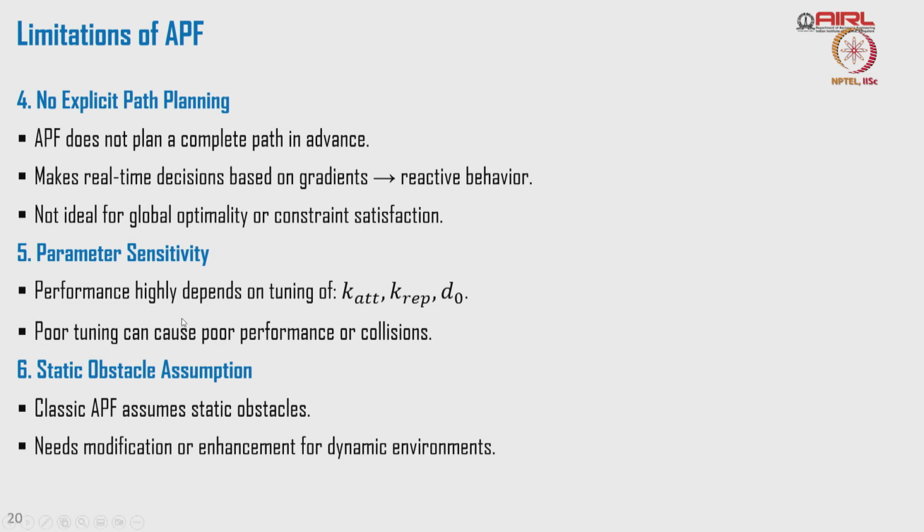If you tune APF with a poor K attractive, K repulsive and D naught, the performance will be poor, which may lead to collisions. APF makes an assumption of static obstacles. Classic APF assumes all obstacles are static, with a repulsive force around the static wall. It requires modification and enhancement for a dynamic environment.